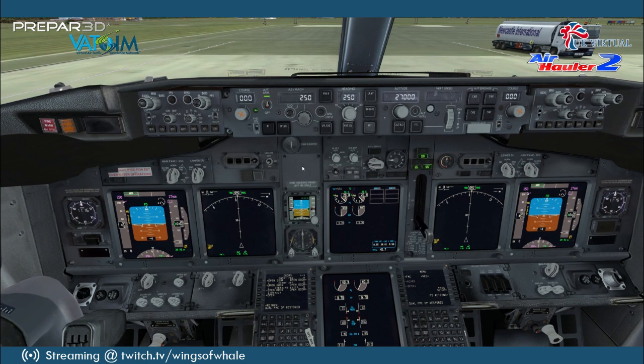So now you would arm auto throttle. That can disarm if you engage reverse throttle. So just keep an eye on that. Sometimes you can activate that by mistake if you pull the throttles down too far back, and I'll show you that actually.